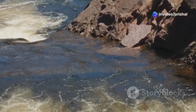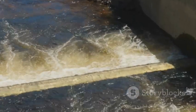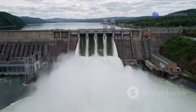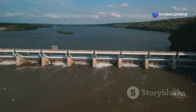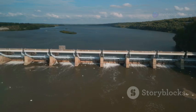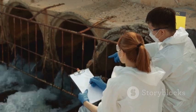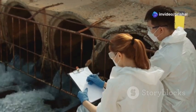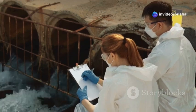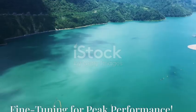These ingenious structures provide a series of steps or pools that allow fish to bypass the dam and continue their journey. We also need to carefully manage the flow of water downstream of the hydropower plant. Releasing too much water at once can cause erosion and harm aquatic habitats, while releasing too little can disrupt the natural balance of the river ecosystem. By carefully studying the local environment, consulting with biologists and ecologists, and implementing mitigation measures like fish ladders and flow management plans, we can ensure that our hydropower plant is a responsible steward of the environment.